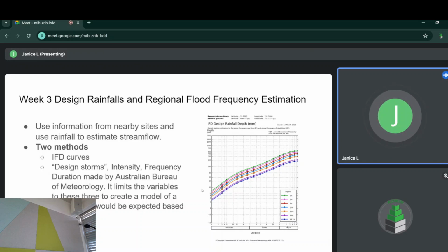That's the whole thing. You use these graphs, you have the AEP, you have the location. From there, you can look at models, design storms, and estimate, well, if this storm were to happen at this place next year or something, this is the depth we're looking at. And then maybe that can inform your infrastructure. Do you elevate certain housing? Do you have drainage to accommodate these kinds of rainfall amounts? And so on and so forth.